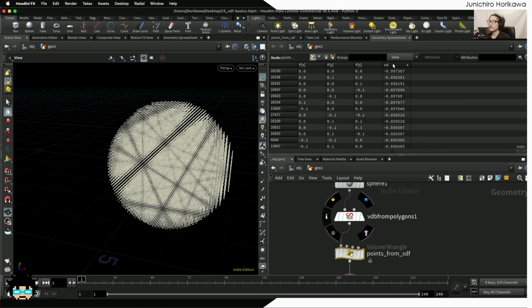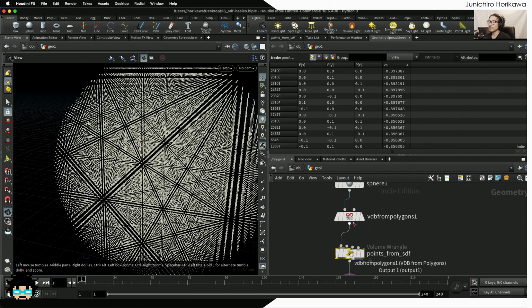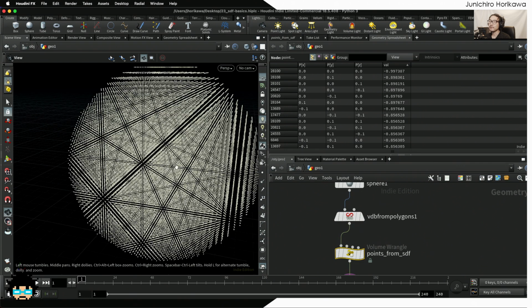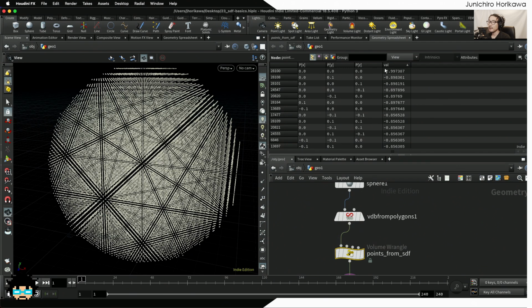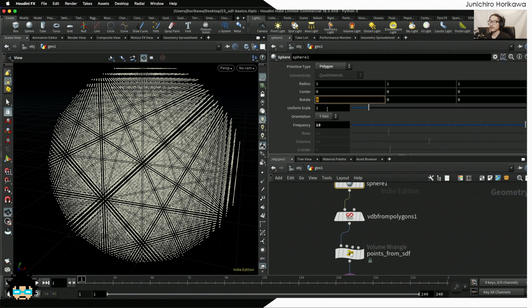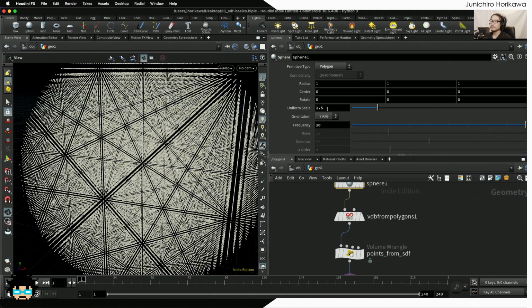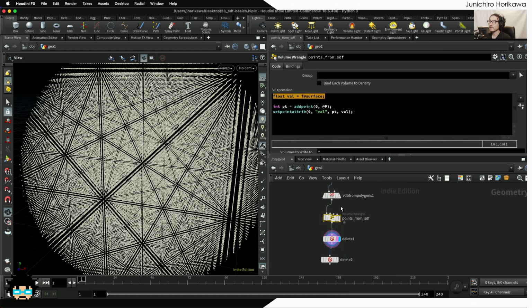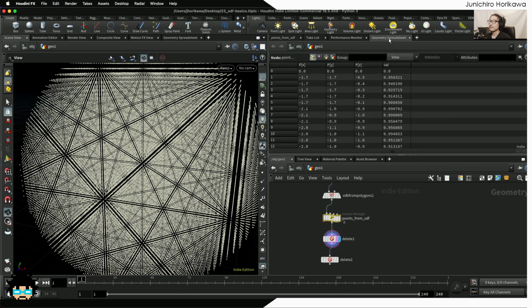Now for the negative value, I'm using fill inside to automatically fill all the values. So it's going to be automatically determined by the size of the surface. Currently it says around -1 as a minimum, but if you change the size of the surface like 0.5, then the interior, the negative minimum will change based on that as well.